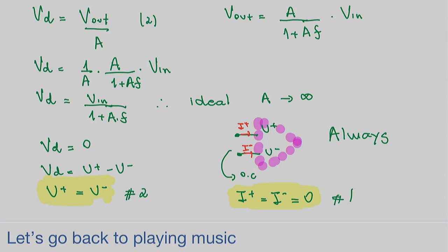We are doing a model, just like we have a voltmeter. When you have a voltmeter, remember the model was an open circuit. Is there current going through the multimeter? Absolutely, inside the multimeter. But those leads, you model as an open circuit. Will the operational amplifier pull current? Yeah. If you wanted to do analysis on every single transistor and resistor inside the operational amplifier, there would be current. But in our model, we use an open circuit.